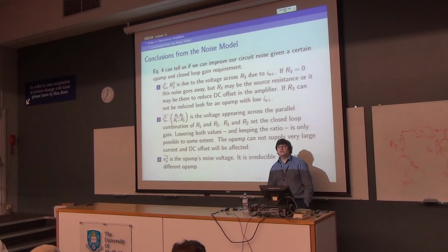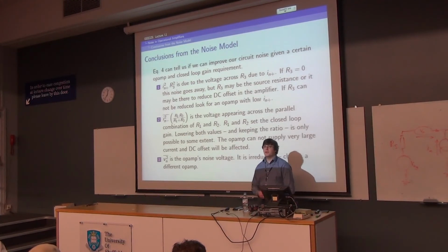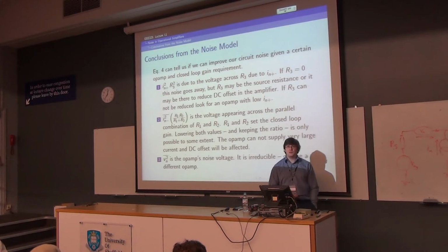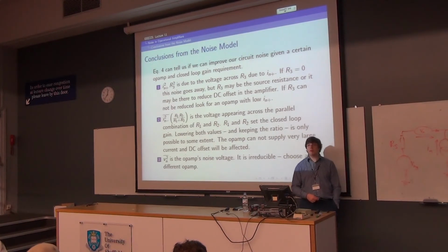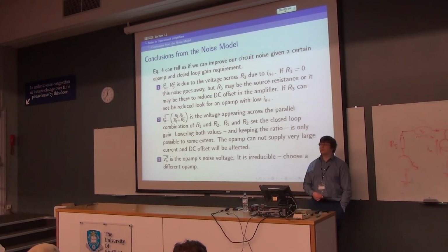If you reduce your feedback resistors to 1 ohm and 0.1 ohm and hope for a gain of 11 or minus 10, you can't do that because 7 milliamps will flow, because that's all that can flow. You won't develop the right voltages because the resistors are too small and your op-amp will get a bit hot and then it will decide it wants to go to sleep.